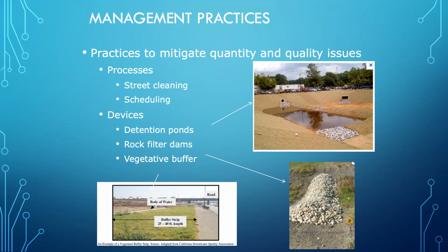And the purpose is, if, say, the flow is from left to right, what otherwise would flow in this ditch, if it's big enough, there'll be some ponding. And in that ponding, solids can deposit. The residuals form on one side of the dam, and they protect the water quality moving on its merry journey down to the receiving water.